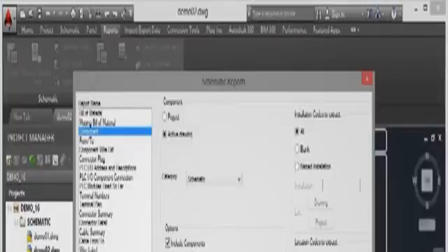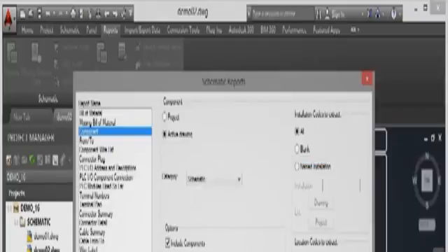Now, if I click on Format here, though, what happens? I can select from report setting files listed below. Now, there aren't any at the moment. I could go and browse for some if there were some available, but there aren't any. All I'm using is the default settings for this schematic report. Installation codes I can set up, blank, quite often useful. And then I click on OK, and there's all the information. Now you'll notice there isn't actually that many components in this specific drawing. You can see them there. So there's your format for your report in AutoCAD Electrical.